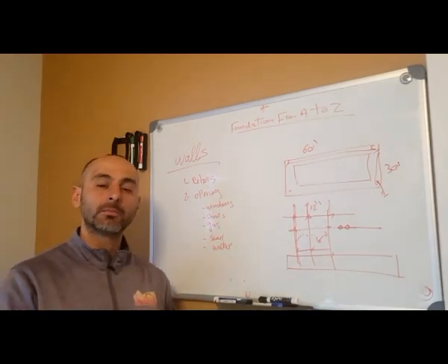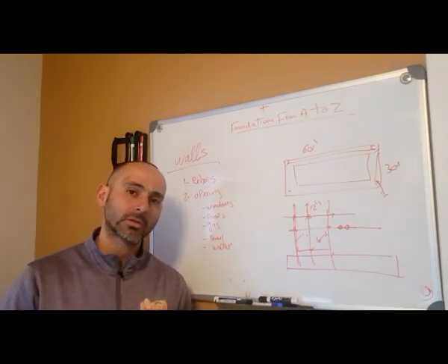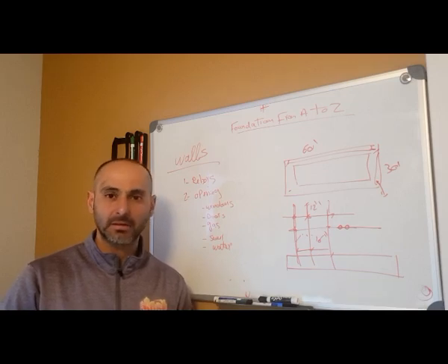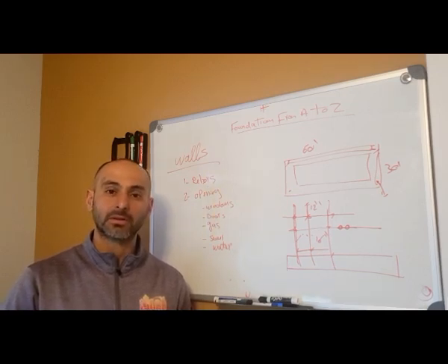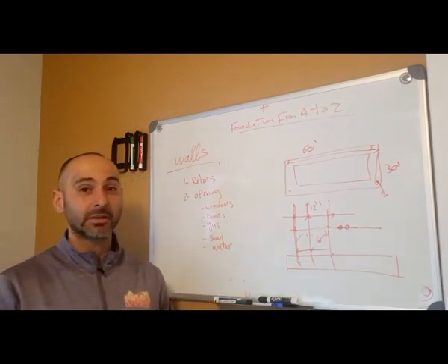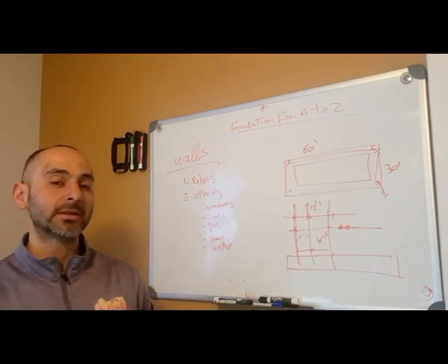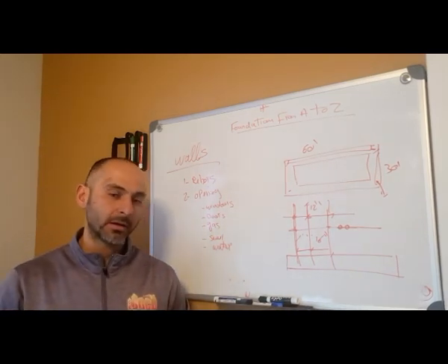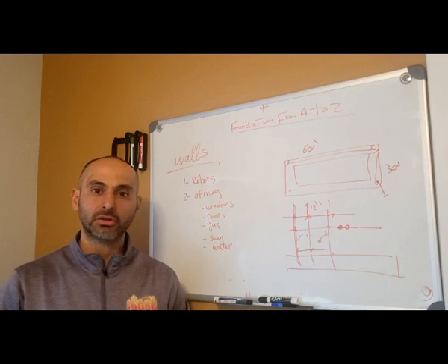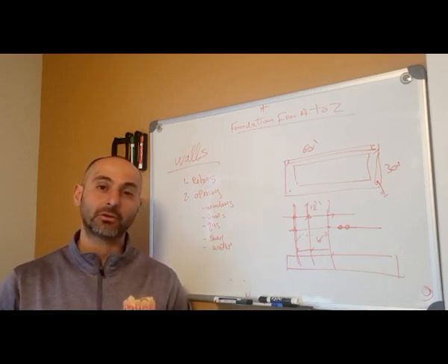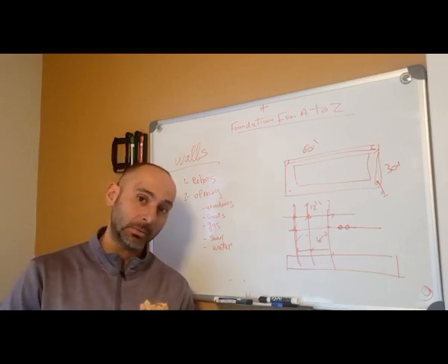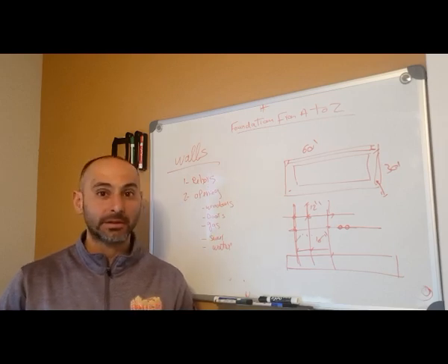Also check the plumb. If you're using a wall system, make sure you plumb the system and everything is good. If you're using block, which I don't recommend on basements anymore, because with blocks you have a lot of masons who sometimes rush, you get a lot of failed joints, and these failed joints can seep into the house in 10 to 15 years, you don't know when.